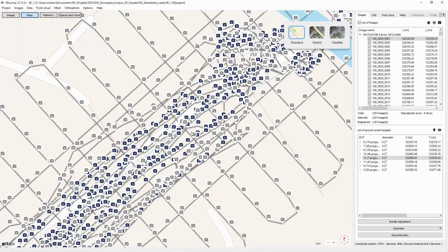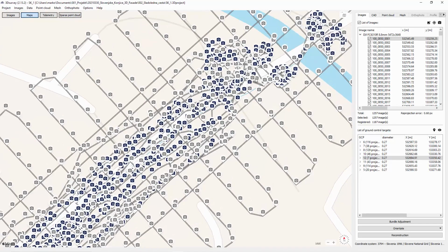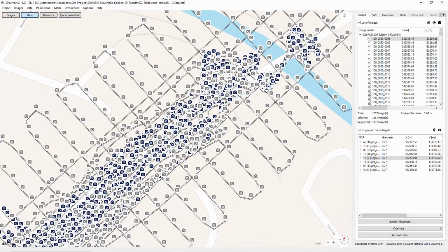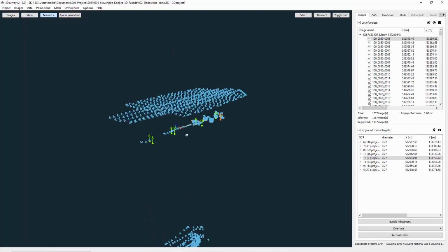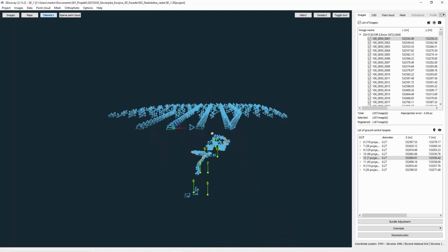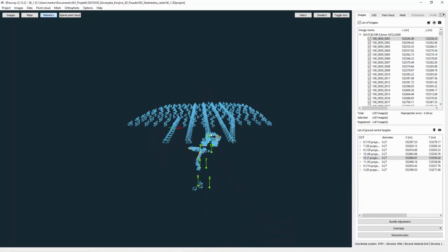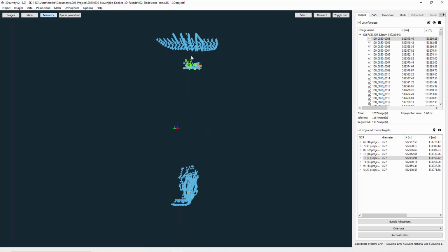On every icon the camera was triggered, and when we were deciding on a flying method, we decided to first do a double grid mission flight. You can see this one here in the telemetry view, and then we also added a lot of manually triggered images. We can see here a really big height difference in between.